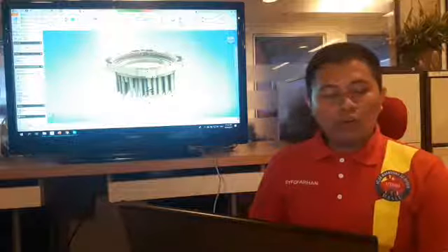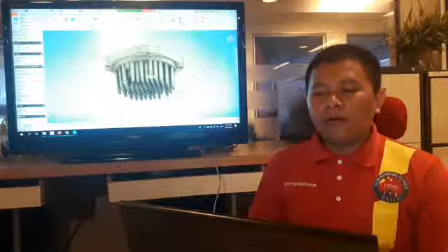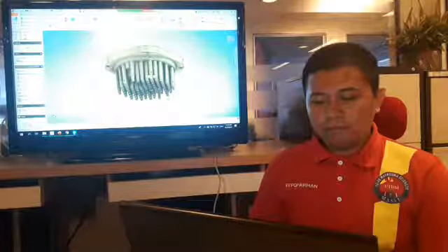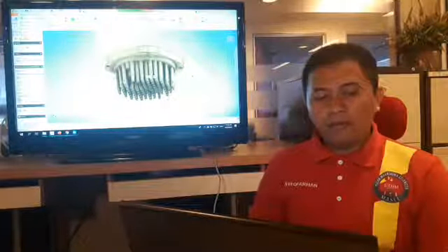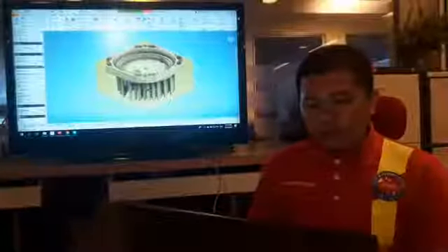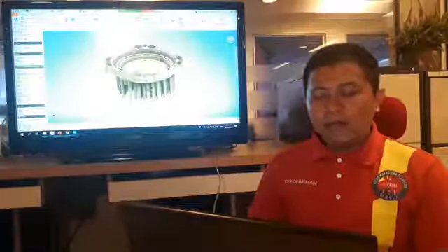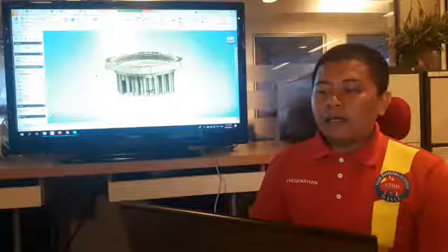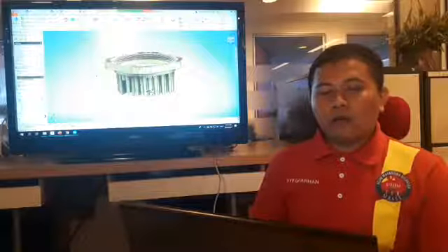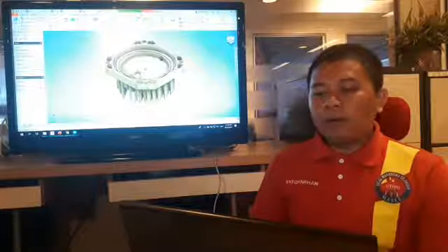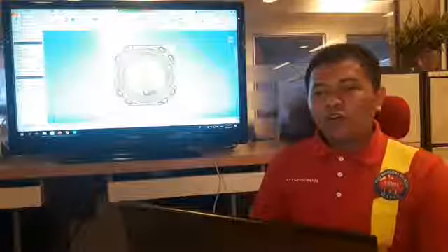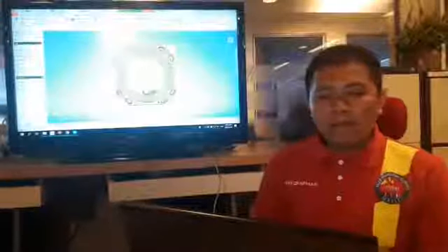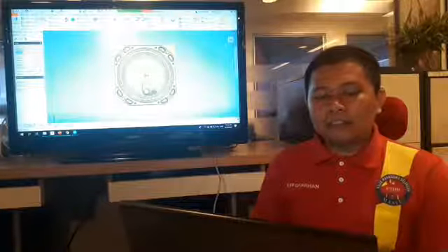Okay, so when you already choose at the bottom over here, it means that after this will be the 0, 0 coordinate when you set the machine. Alright, done. Then I just go to the stock over here. For example, I want to make my stock a little bit bigger when I start the machine. So I go to the fixed size box.